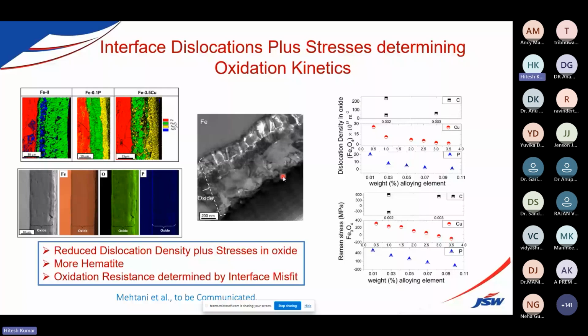We never try to tilt the beam, because to align the beam again is a big task. So most of the cases we tilt the specimen and try to align it to one particular point, that is called the dark field image. So in this we are basically taking the image in the bright field mode only.